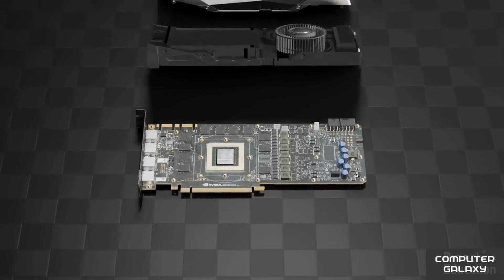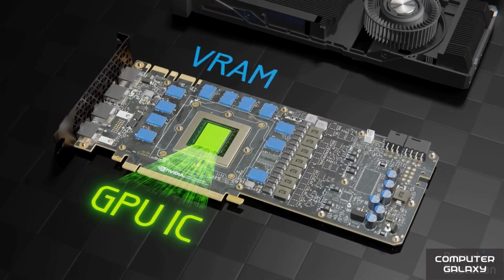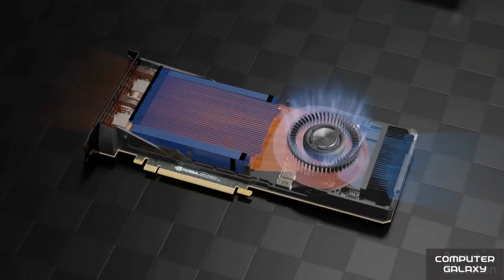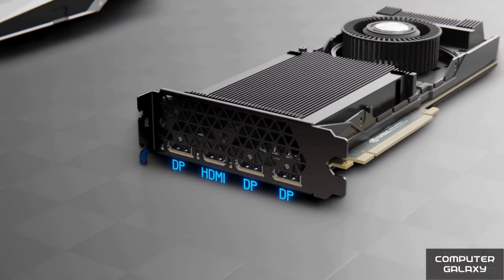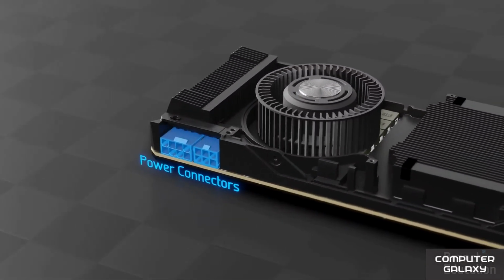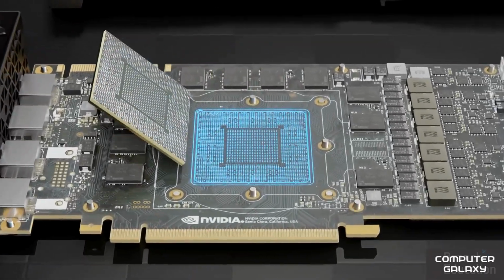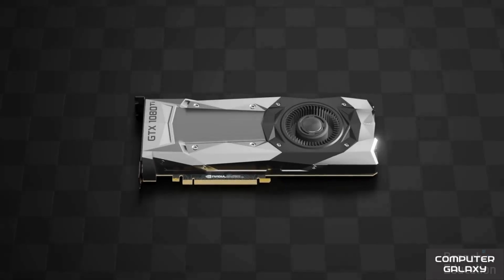Opening the graphics card, we see another PCB with the GPU's integrated circuit in the center, VRAM chips all around, and the voltage regulator module on the side. Above the IC is a heatsink with a fan to dissipate heat, and on the side of the graphics card are HDMI and display ports, a PCIe interface, and then on the other side is the input power connector. Let's focus on the GPU integrated circuit, which, similar to the CPU, has more than 1,000 solder pads that connect to the PC. Close this graphics card and talk briefly about the 3D model.